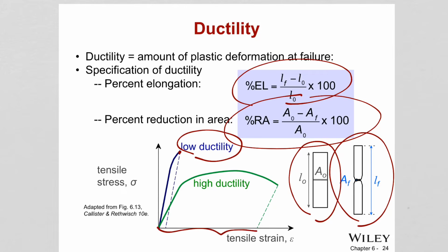You can see it deforms to a large extent. Of course this is the plastic deformation, so it doesn't include the elastic recovery here. Anyways, from looking at the x-axis and seeing how much it is strained, how much it is deformed, you can comment on looking at the stress strain curves: what is the ductility? Is it high? Is it low?